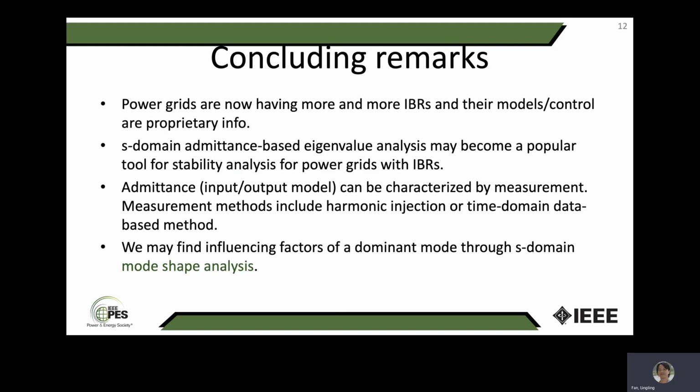In addition to screening analysis, we can expand this admittance-based analysis to do mode shape analysis. This mode shape analysis can help us identify the influencing factors of a dominant mode. And in this case, we successfully identified a 3 Hz inter-area oscillation mode.